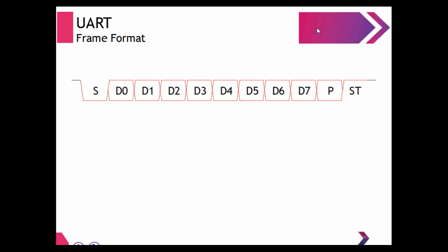Now we saw the frame format. The frame will be in this format. When we are doing communication, you should have an idea of how a frame is generated. Anyway, we are not going to generate any frame. It will be done automatically for us by the built-in UART block. We are just going to configure that block, and that block does everything for us. It sends the start bit, sends the data, calculates the parity for us, and even generates the stop bit. I hope you are understanding my concern, Munir.